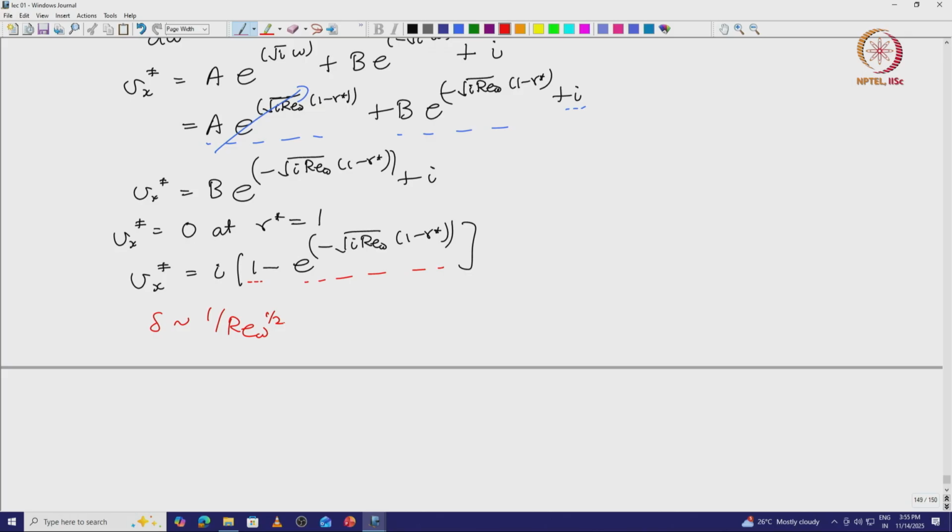We rescaled the equation and then we were able to solve it by incorporating the diffusion from the boundary, within this thin region whose thickness decreases as the Reynolds number increases in such a way that viscous diffusion is comparable to the acceleration and the pressure gradient within this thin boundary layer. And this procedure is what is called a singular perturbation.